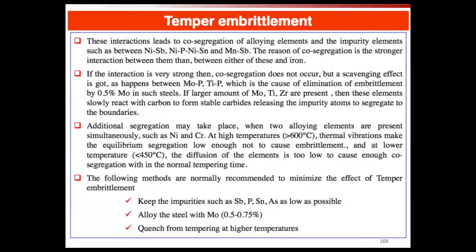Well, in that case, it's cracking of the cementite, but in general, whenever you have something that's going to wet your interface and have low energy, it's also going to be a very easy fracture path. The example at the beginning, I think I gave bismuth and copper, where well less than 0.1% will completely coat.